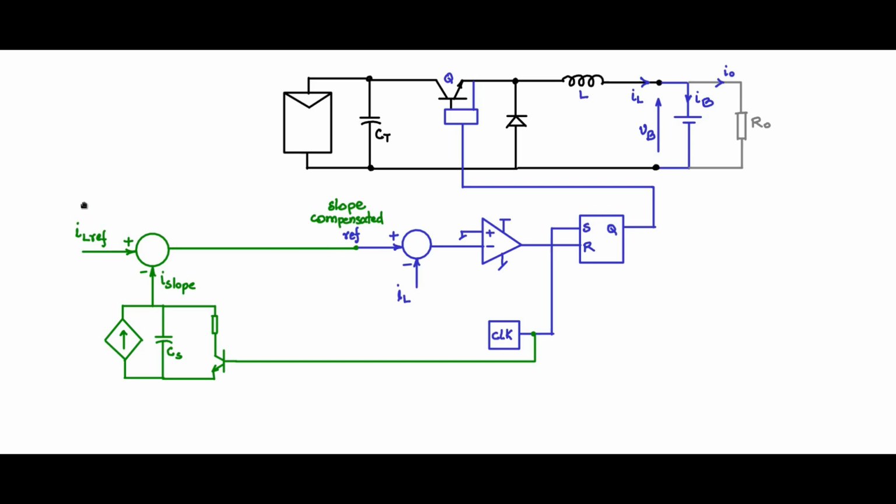Now if you look at this wave shape, it is just the DC. And what about this wave shape? So let us first set the current reference here. The current value is Vb into Cs by L. Observe that Vb is the sensed value, so the current reference here will change according to the output voltage.